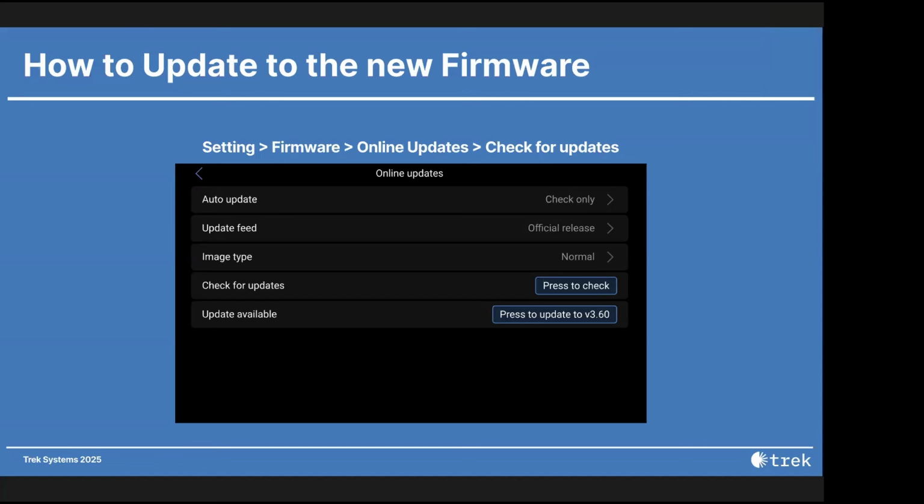And it's being broadcast via the Wi-Fi. But where do you see it? Is it in the device list on Victron Connect, or where is it broadcast? When you go to attach a wireless device. So theoretically, any bad actor walking around a campground could see everyone's serial numbers. I can change the display name of my MPPTs and stuff, but I can't change my SSID. Now, the serial number is not used to connect to VRM, right? That's your VRM portal ID. Portal ID connects to VRM, in order to actually access a VRM account or set up a VRM account.